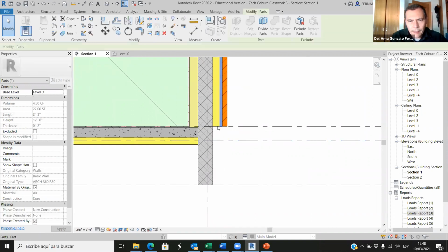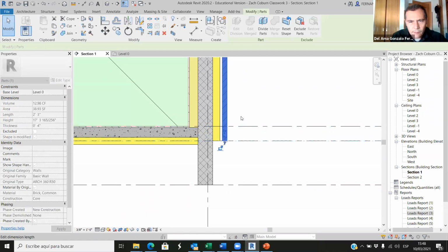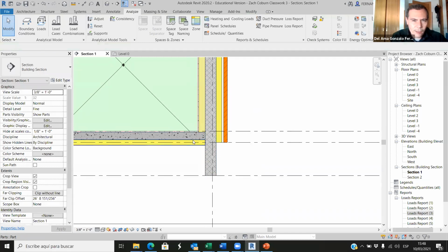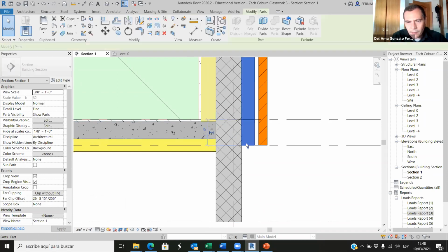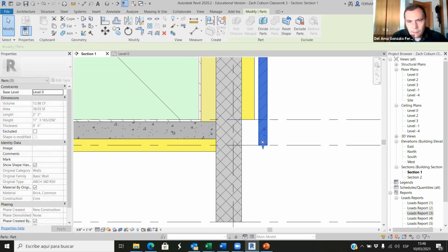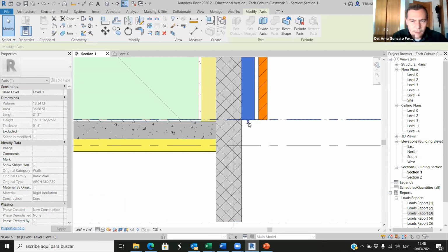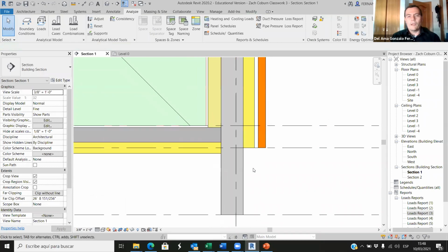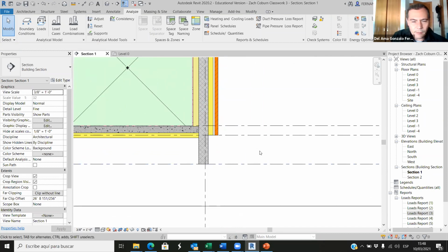And yeah, I can move this down up to this level and this up to this level. So here we don't have the thermal bridge, or we have a thermal bridge, but at least it's not as bad as doing this. Okay, so this is worse because we have all this front without any thermal insulation. At least if we move this down, that's better. And finally, we would need a footing here.